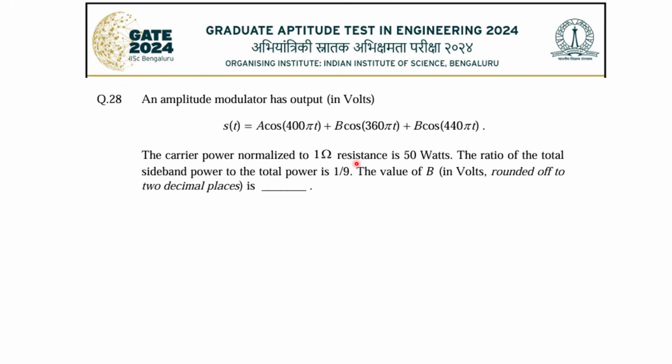So it is very clear that the deviation is 20 hertz. 200 is the carrier frequency, and plus minus 20 deviation is the message information. This belongs to the carrier, this belongs to the lower sideband, and this part belongs to the upper sideband.